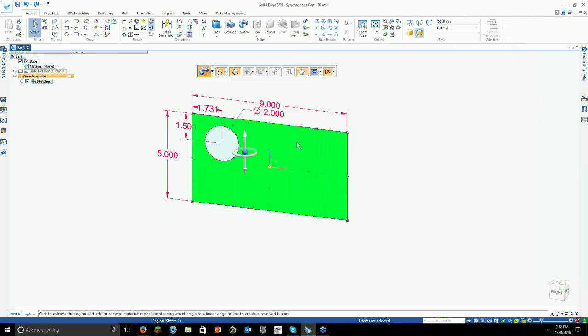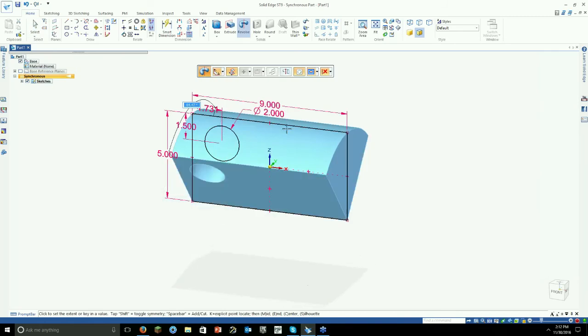All right, so let's do that with revolve. So I click revolve. You notice we get a different look on a steering wheel. So right now, to move the steering wheel, you pick the little ball in the middle, center bearing. So that moves it to different locations. So if I grab that edge, you notice it snaps to that edge, snaps to particular edges that you want to go to. Let's say we want to revolve itself around that edge right there. So it attaches. Then you just pick the torus, and it goes into a revolve mode.